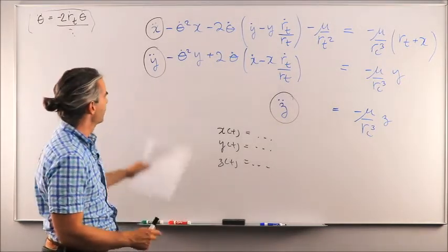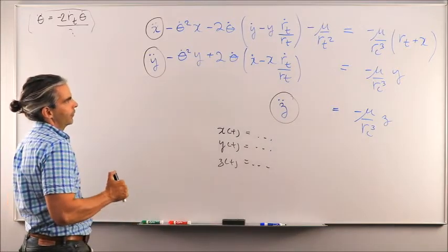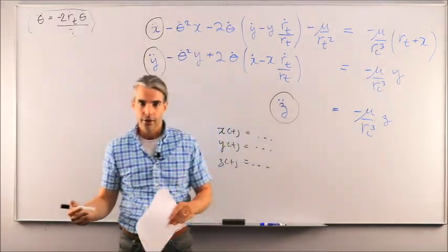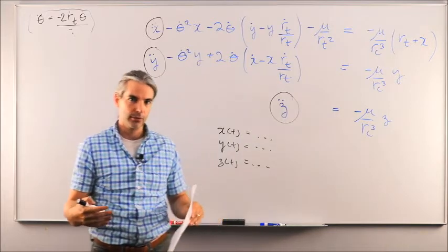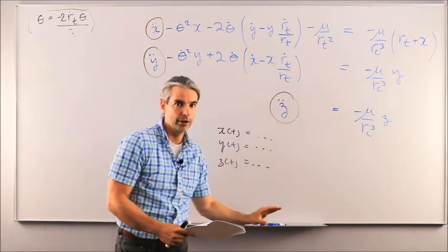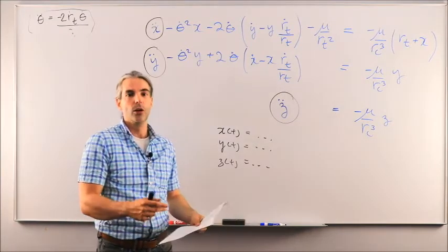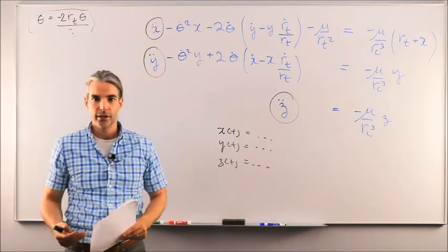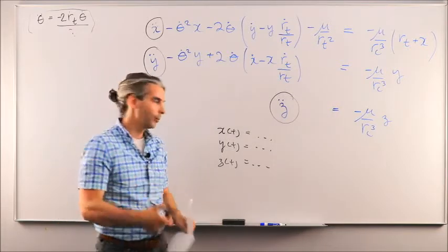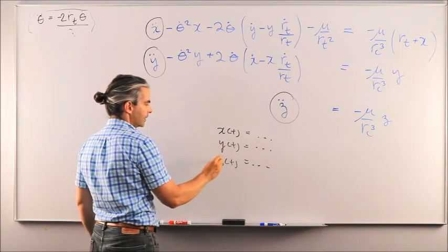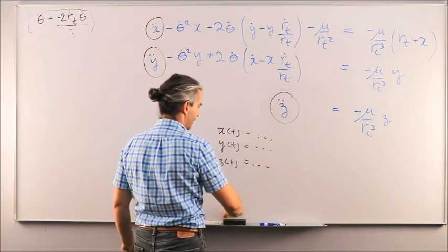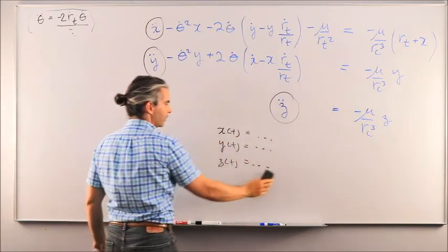So the bulk of the remaining work in that section is to figure out a way to simplify these equations down to a simpler nonlinear equation of motion model. So we'll still be talking about nonlinear dynamics, but simpler, such that that simpler nonlinear equation of relative motion will be linearized eventually. And then once we have obtained the linear equations of relative motion, we will be able to express x, y, z components of the relative position vector as a function of time, okay, and get explicit solutions for the relative motion.